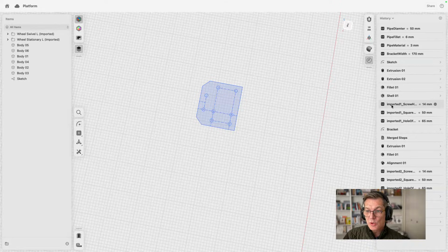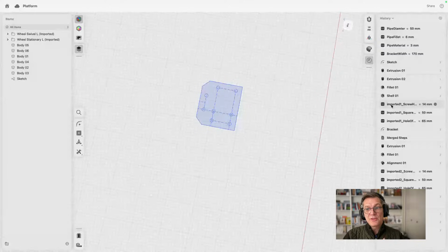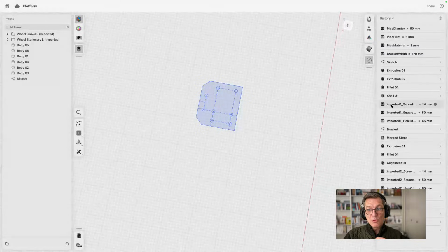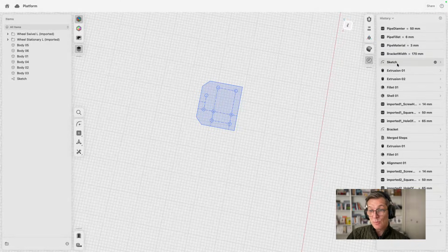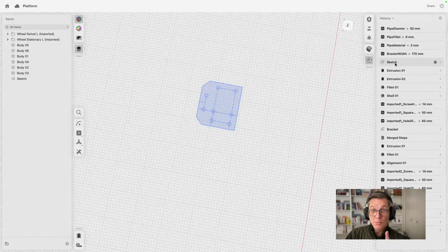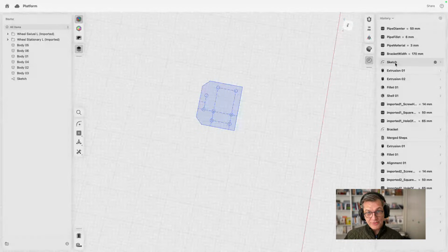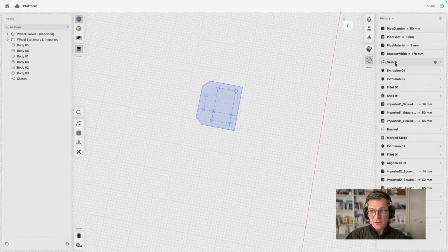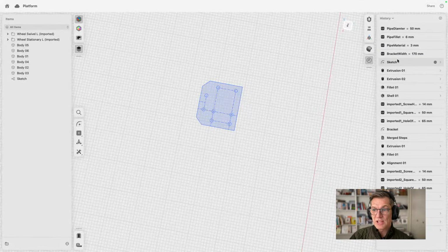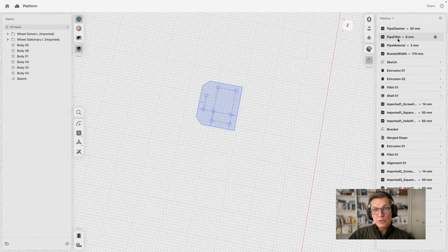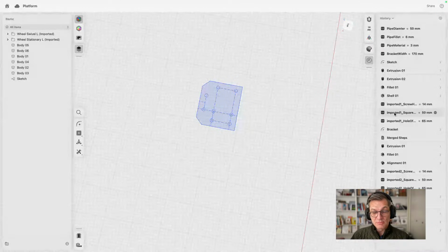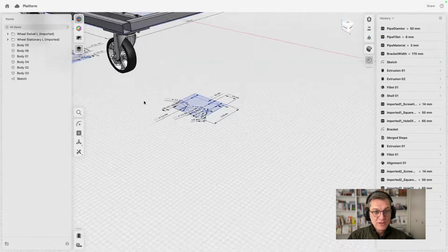I cannot with later variables adjust a sketch or modeling feature that happened time-wise before. But if you work with multiple files individually and you bring them then together, what you then could also create is create then a new variable. And then a variable I created here could then be inserted and drive a variable that was created later. Just to answer that question.